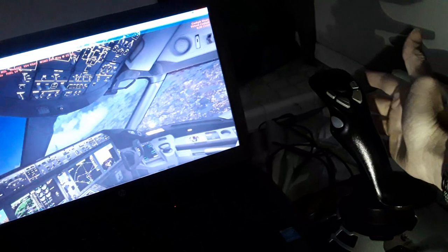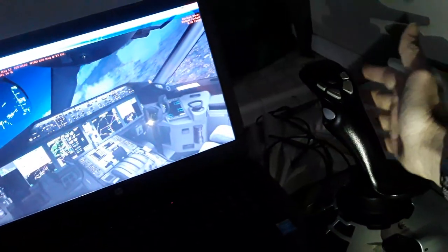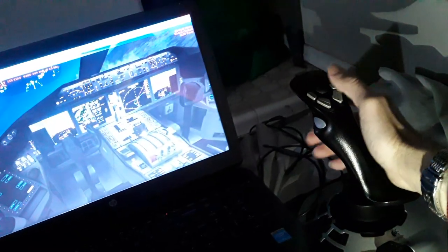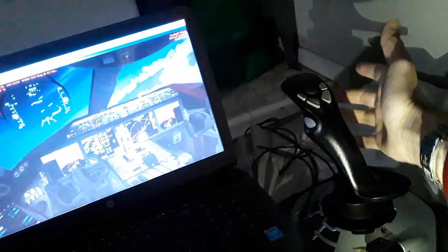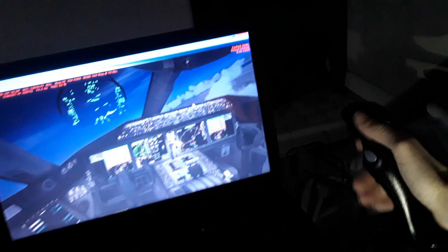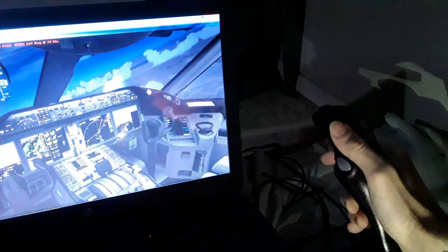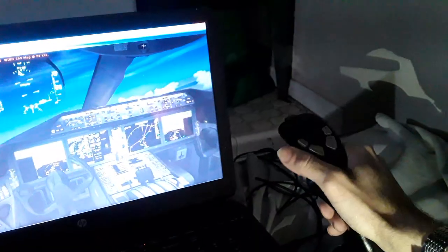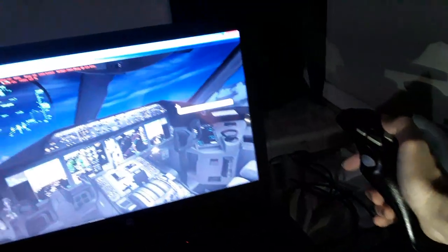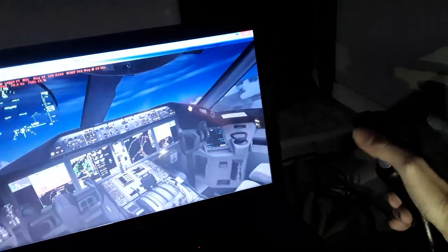See how easy it is to turn, and you leave the flight controls off. There is no problem holding the flight controls. Level, again, flight controls off, no problem, because we have trimmed the aircraft and we have set the thrust we need, and we keep the attitude as we like it. It's also a fly-by-wire aircraft, so you can trim and make some flight controls by itself.